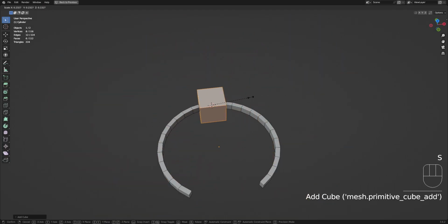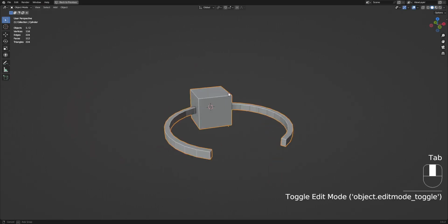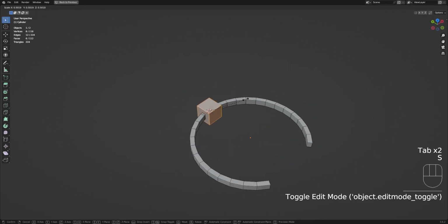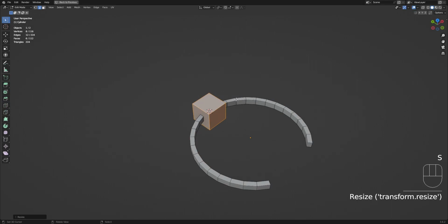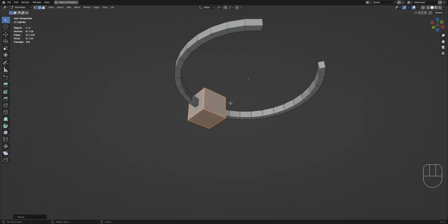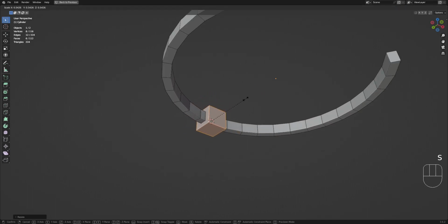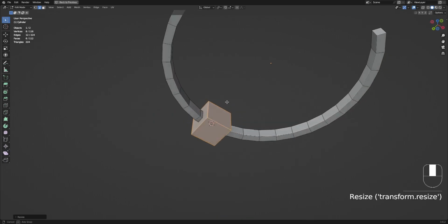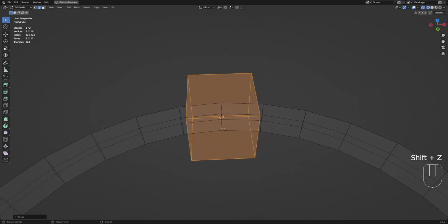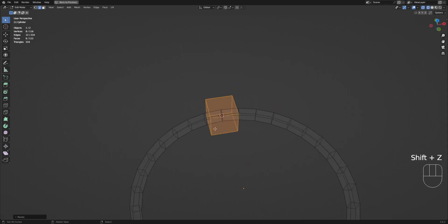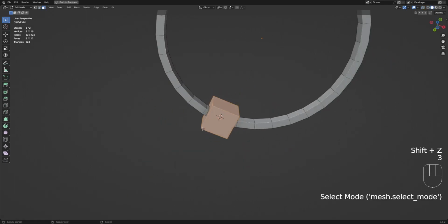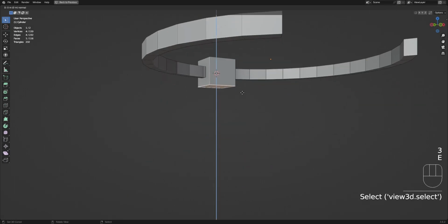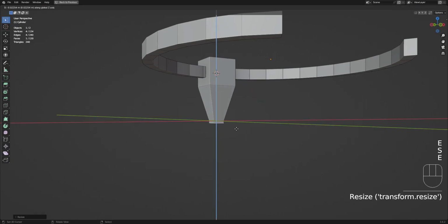I'm going to scale that like this. I'm not going to use Boolean to merge it to this. I'm just going to join it in edit mode while not making it a unimesh. So let's just leave it at that, just to have fewer problems with the topology later on when we use Random Flow.